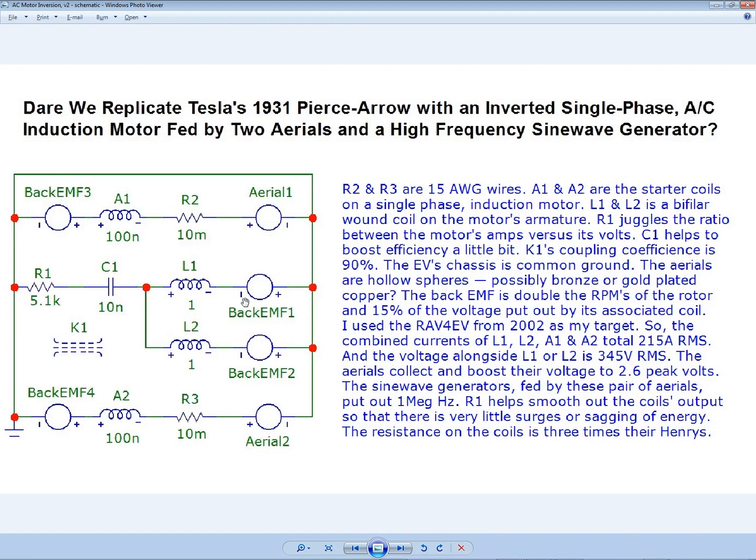It takes far less of a portion of a second, which in real life would not seem like much, but from the standpoint of a motor, every time you turn it on, do you want it to surge to 2 kiloamps? You'd probably fry the coil momentarily, but you keep doing that. Every time you turn on the motor, it's going to wear out the insulation on the coils. So putting this resistor in here is a godsend. Now it's obviously going to heat up. Everything here is going to heat up, so that's normal. You just deal with that.